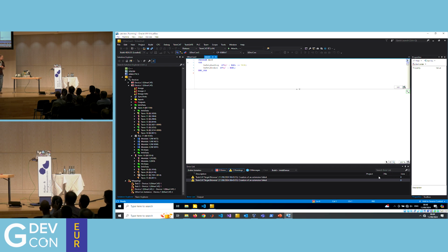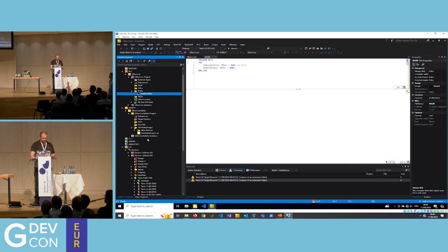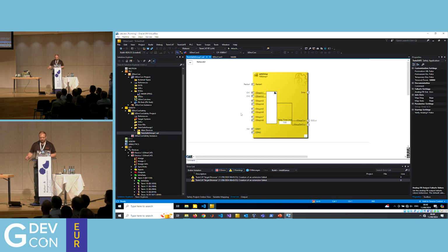Okay, thank you. Maybe we could watch it later, but a short question. What is the exact role of the so-called safety module, which I also spotted somewhere in your demo? Yep, so the safety module, this is just how we develop the safety projects in TwinCAT. This bit here you're referring to. It's doing nothing more complicated than running an e-stop. It's a continuous function chart integration that we use to build up safety networks. All it's doing is running the functional safety terminals on this device, which I can show you when I get it working again.